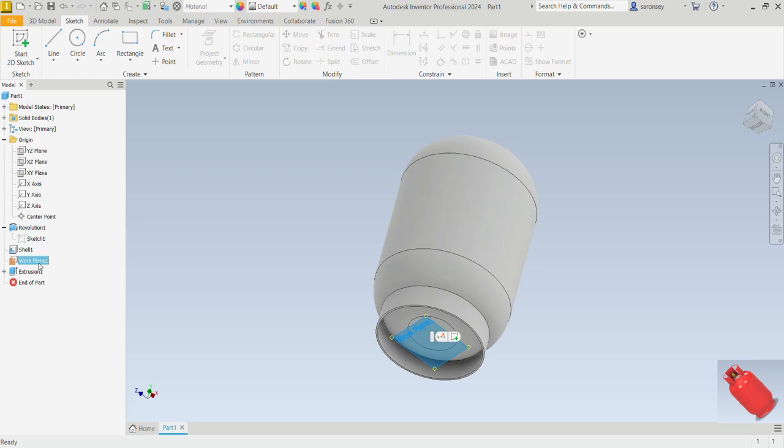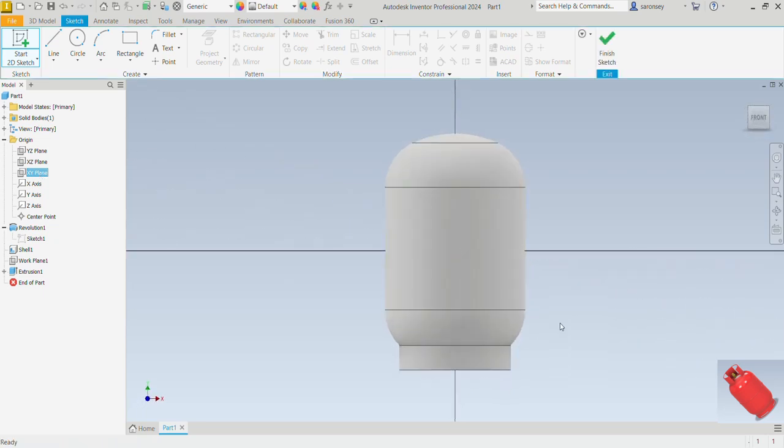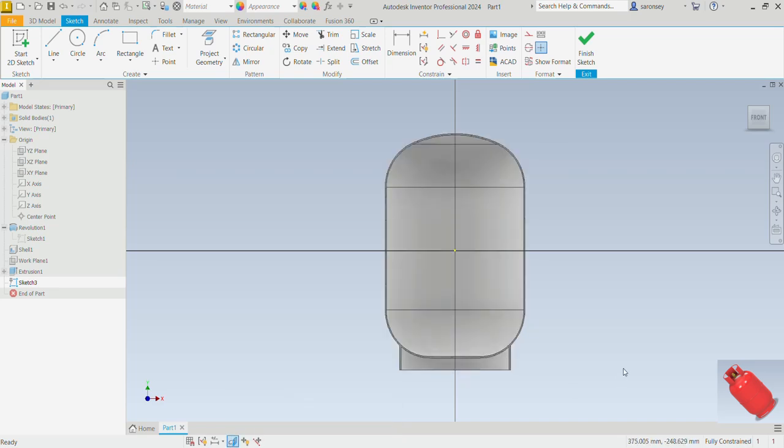You can go ahead and turn off the visibility of this plane. Next, we want to create the vents on the stand. And so we'll pick the 2D sketch command. We can create that on the XY plane, but we don't see the plane because it is hidden. So I'll choose this option down here that says Slice Graphics.